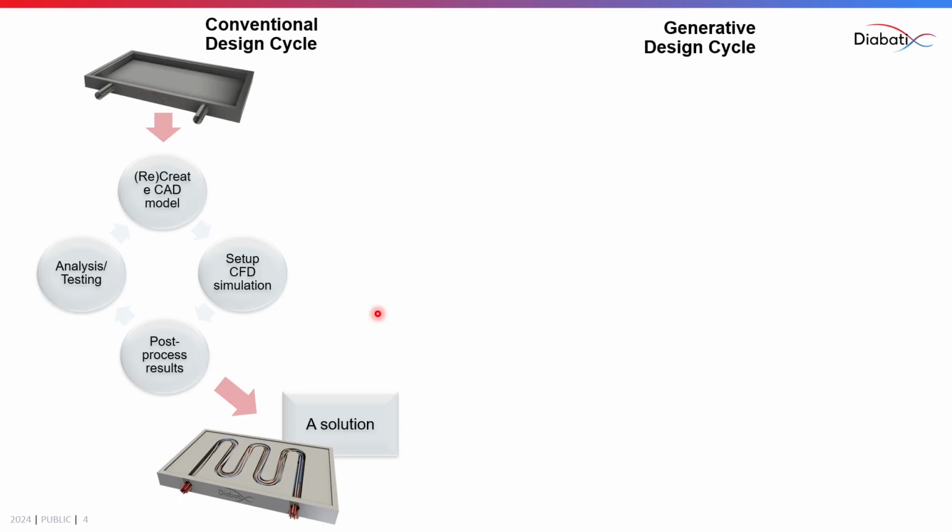The later part will come in the case of thermal management, where proper designing of heatsink is necessary in order to extract the heat out of the system so that it will function to its maximum performance. The reason we need to have heatsink is because the heat accumulation, if it is not done properly, can impact not only the behavior of the component or behavior of the electronic devices, but also it can affect the longevity of these electronic devices. And this essentially gets translated into a CAD model, that is the PCB design and heatsink design.